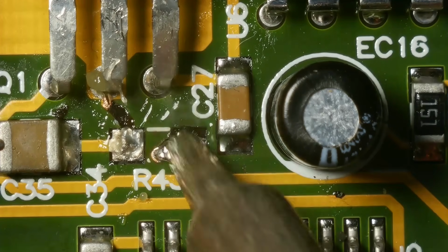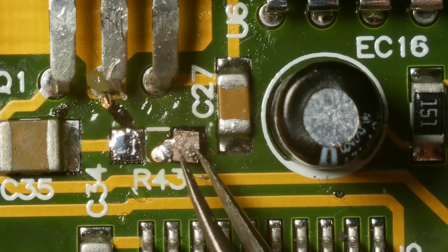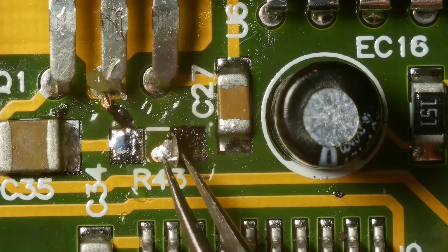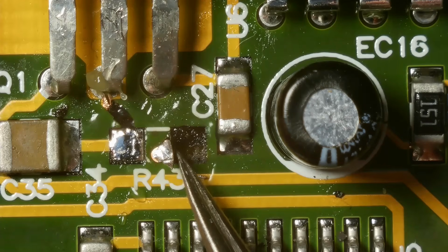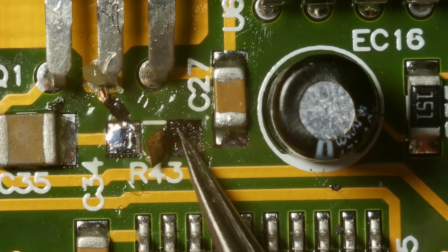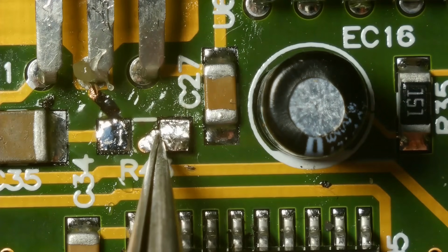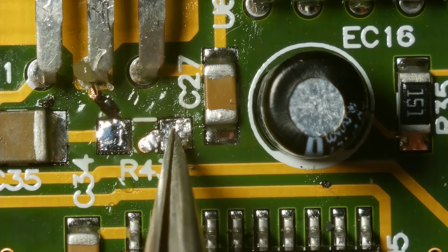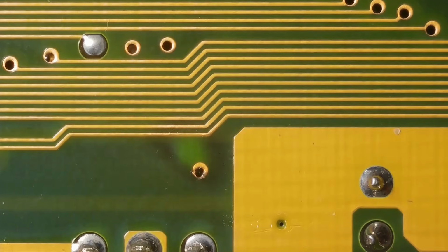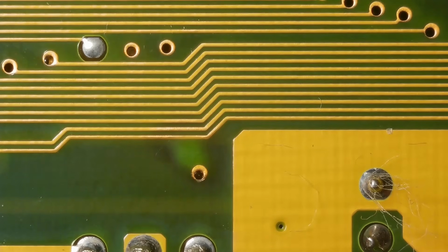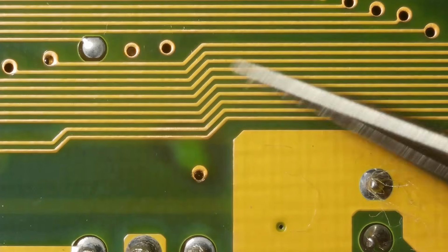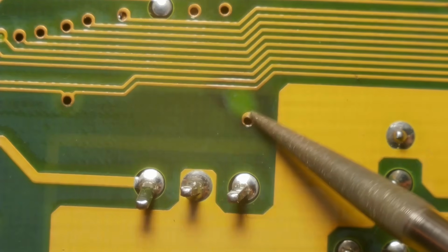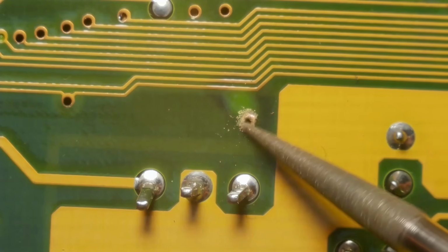Unfortunately, also this pad is lifted. The PCB was exposed to a very high heat here. I probably could glue it back, but there is a wire nearby, so I'll better try to solder a wire there. This is that wire from the other side. You can clearly see a discoloration of the PCB around it. Looks like a lot of current shot through this point. I will try to replace the old resistor with a wire through this via.